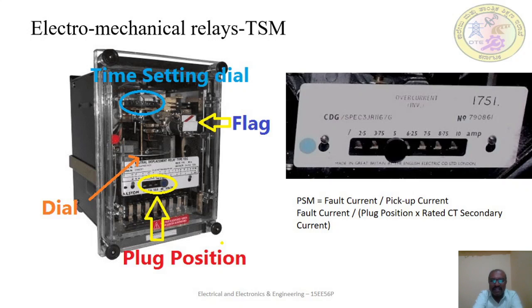And the second thing is the rapid disconnection of the faulted element limits the amount of damage to it and prevents the effect of the fault from spreading into the system. And how will it happen? The detection of fault and disconnection of the faulty section or element can be achieved by using fuse, as we have discussed in previous sessions, or relay. In this session we will discuss relays in conjunction with the circuit breaker.